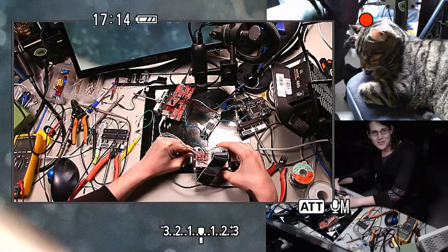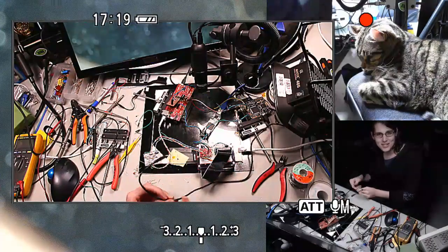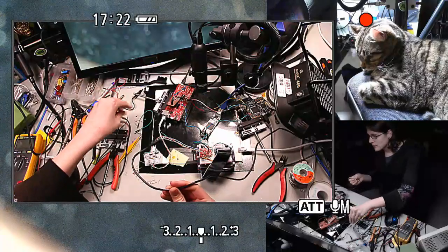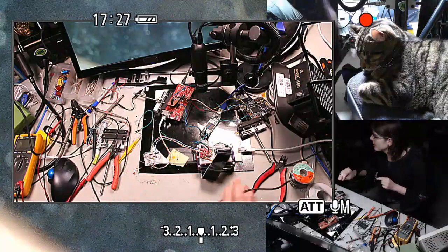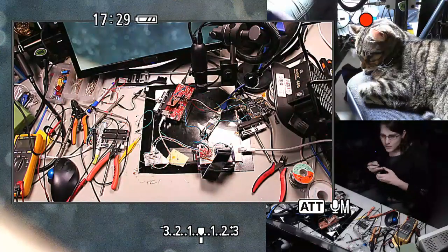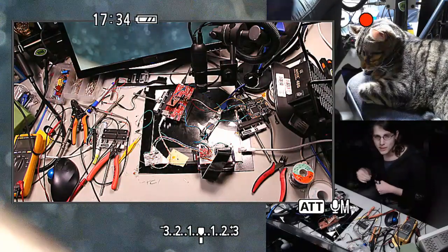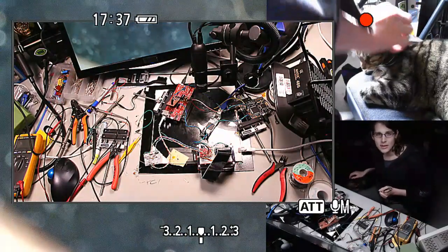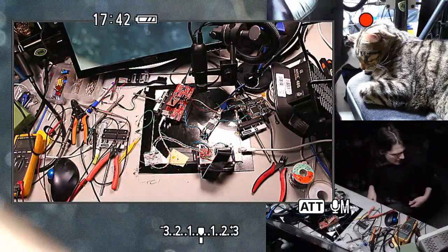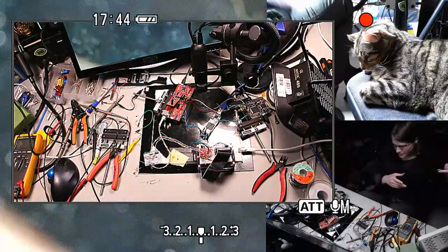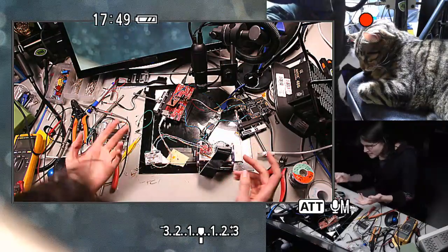Just taking some resistors in this range, in the high two digits and low three digits, and trying to bridge the two signals together while keeping them DC biased to an appropriate level, with at least 50 ohms in between them, I'm not worried about the currents flowing that would cause damage. It's just a matter of signal integrity, I think, at that point. But yeah, I tried a few things like that and didn't happen upon a combination that seemed at all effective. I mean, sometimes I would get link test pulses through.